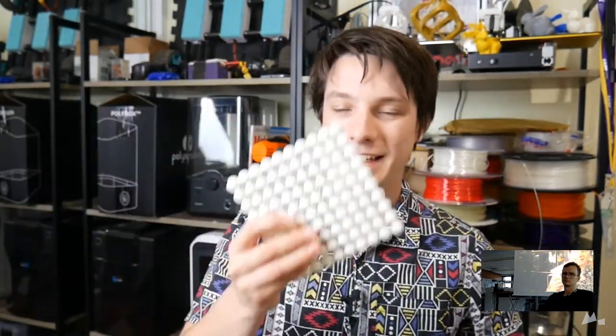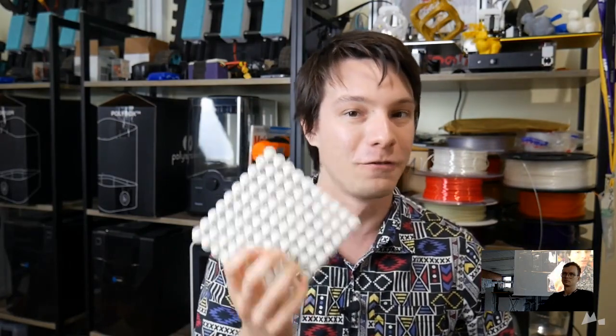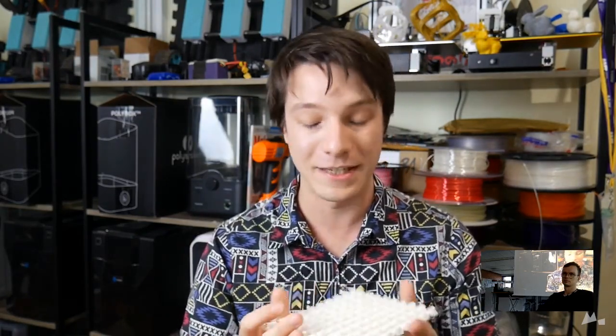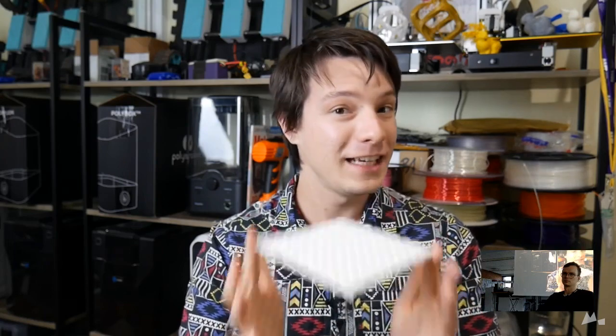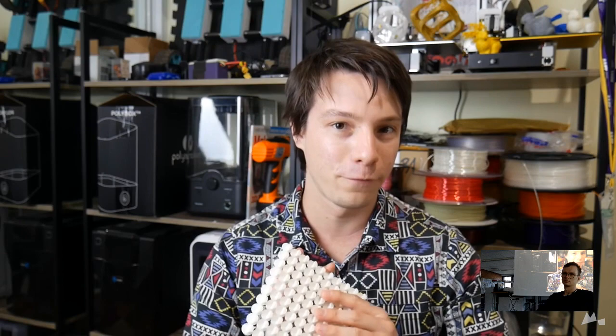You can guarantee that this part has a very low recycle percentage. In fact, it might actually be pure virgin powder. And that leads me on to the next point. To run these machines, you need to have a pretty much full build chamber. Cool 3D nesting, I mentioned at the start of the video, and that's why SLS systems are fantastic for high volume print bureaus and probably terrible to own at home, because you're not going to be able to print one thing. You're going to want to print a lot of them all at once in your build chamber. Like I mentioned, you can stop it at a Z height, but your X and Y needs to be used.